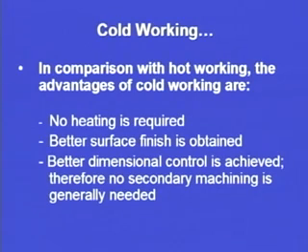So, as we have seen, volume of production is directly related to the cost that we have incurred in setting up of the equipment. So, setting up of the equipment also includes a furnace where we are going to heat the metal. So, if heating is required, there is additional investment in the form of a furnace, whereas in cold working we do not require to heat the metal. So, when heating is not required, the furnace is not required, so the cost incurred at the initial setup will be comparatively less. So, no heating is required in case of cold working.